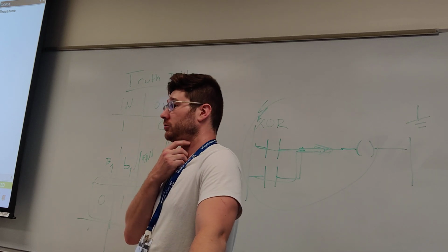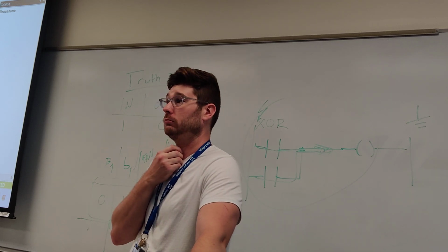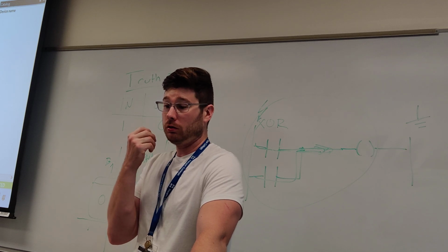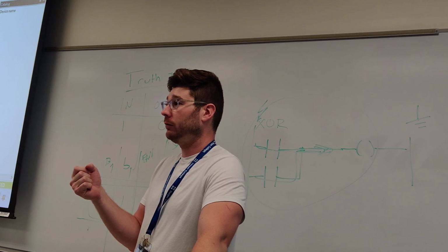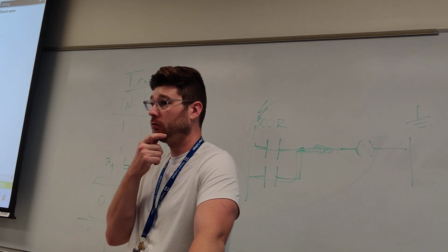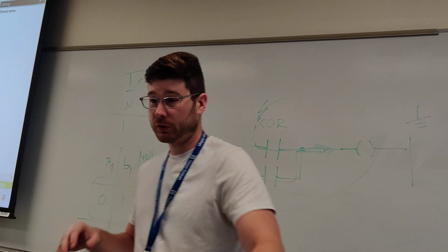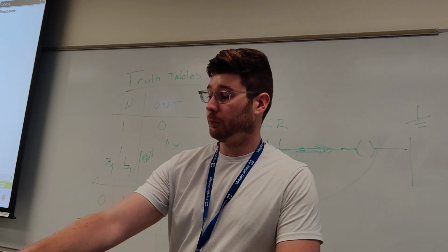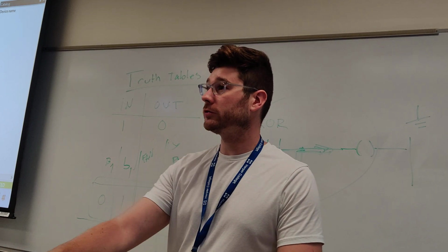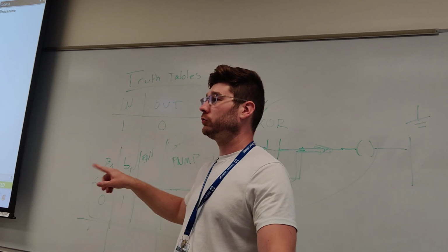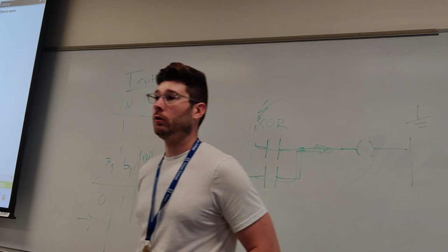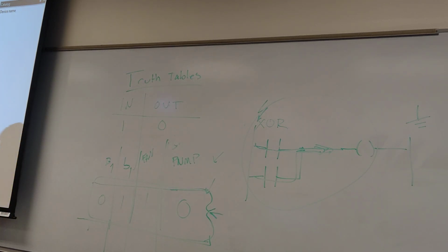Okay, do we feel like we kind of understand structured text and ladder logic a little bit? All right, so let's do 15 minutes of making some sample programs. Don't worry about wiring, don't worry about the switchboard just yet, but use this button, use the onboard LEDs, mess around with negating the inputs and the outputs. Just play around with it for a few minutes, and then we'll go on with the lab. Do you have any questions? Let me know. If you're struggling, let me know. But let's get into the inputs.